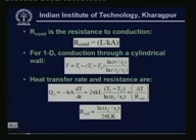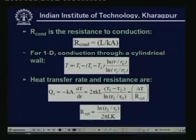Let us say that you have a thin cylindrical wall, and if you apply an energy balance, then you get the basic heat conduction equation, and if you solve the heat conduction equation by applying suitable boundary conditions, you arrive at the solution for temperature. This temperature profile is logarithmic. In the case of Cartesian coordinates, we had a linear profile, but this profile is logarithmic, and by differentiating this using Fourier's law, you can get an expression for heat transfer rate in cylindrical coordinates.